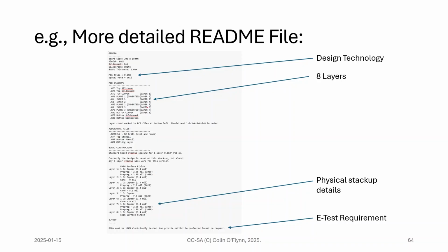And so I mention in here all the layers, including inner layers and plane layers. Remember, plane layers mean I have connection basically everywhere, so that whole layer is used as a plane layer, as one net, or maybe a few nets, but there's not a lot of traces on it. And inner layer, I'm just using for traces. So there's no difference in the actual construction of it. It's just a difference in the nomenclature. And in this case, there is a minor difference in the file that I'll show you in a second, because you'll notice it says inverted in all the plane layers.